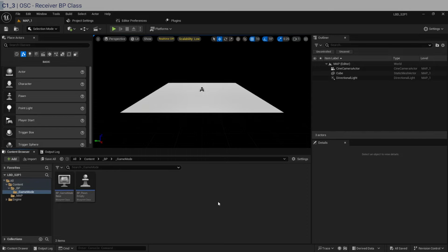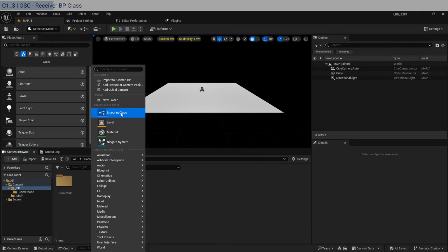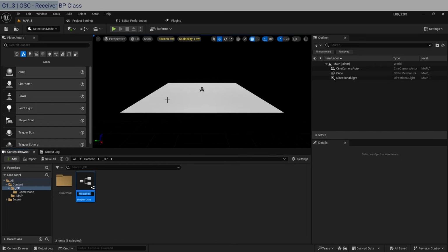Okay, so once your Unreal Engine has restarted, what we'll do, of course, is to receive OSC messages from Ableton in Unreal, and we'll create sort of a blueprint actor template that you'll be able to use over and over again in your future audiovisual projects in UE5. Let's go over to the blueprint folder and we can create a new blueprint class, actor, and we'll call this BP_OSC_T1 for template 1, let's just say, and enter.